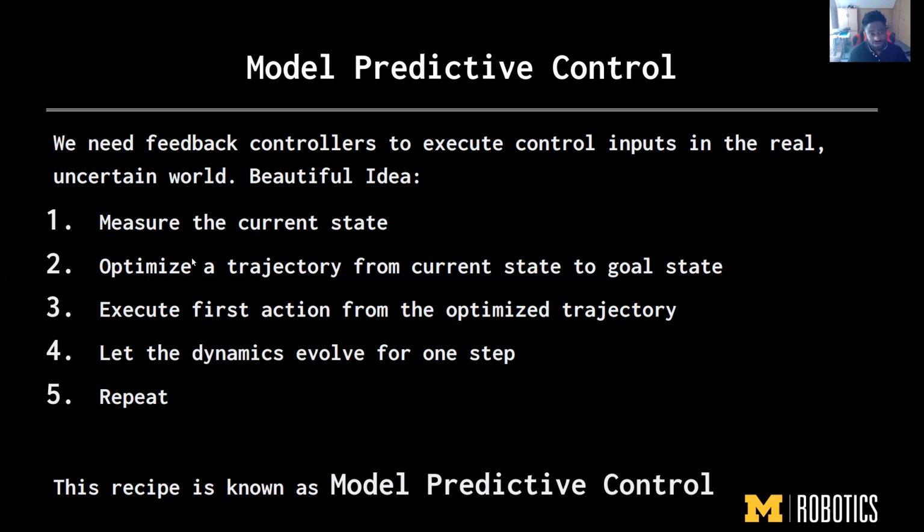And so for optimizing the trajectory, you don't just have to use trajectory optimization. You could also use different methods like iterative LQR, which is basically LQR performed iteratively. That basically linearizes the system at multiple points. So for instance, if you want to use iterative LQR with an MPC, you first linearize at your current position, perform the optimal control, and then you linearize again, and execute it, linearize again, and execute it. Perform that multiple times to end up at your goal state.